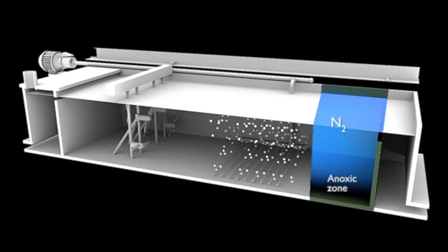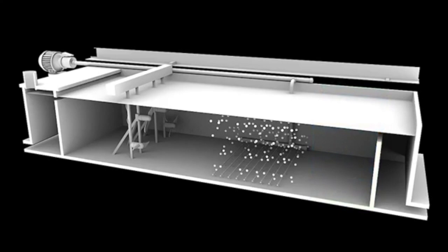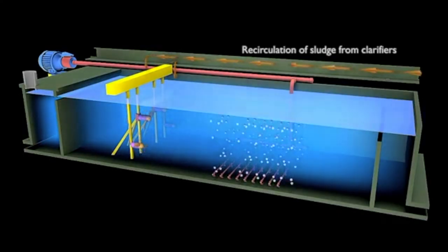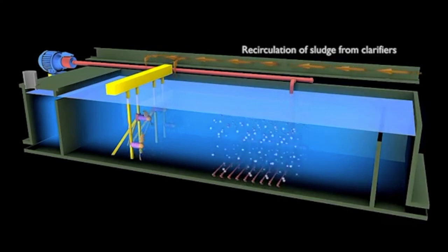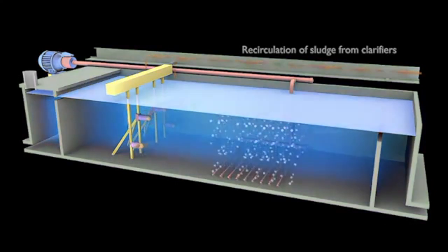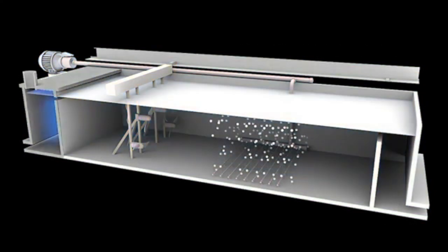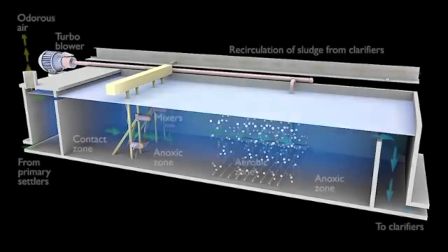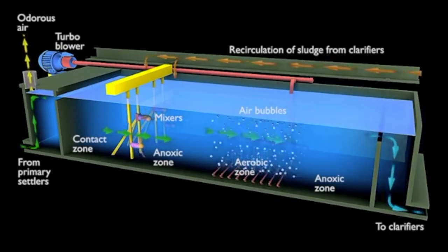The disturbances that affect the performance of the process are pinpoint floc formation, filamentous bulking, dispersed growth, and zoogleal or viscous bulking. To ensure a good balance between food and microorganisms, the bacteria settled in the clarifiers are continuously returned at the inlet of the tank.